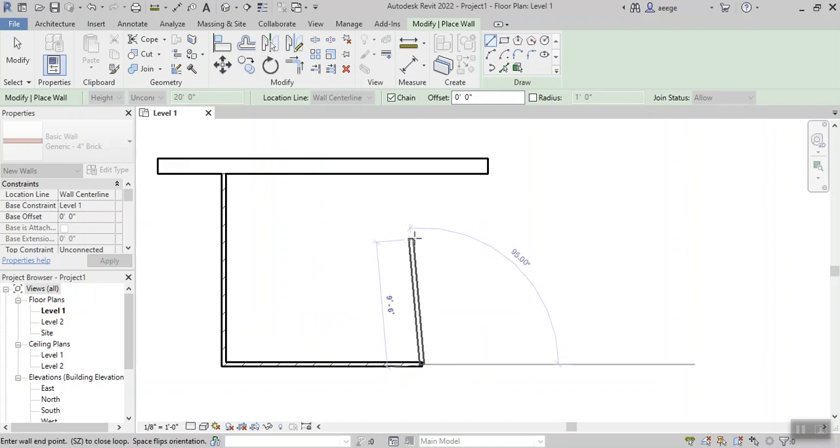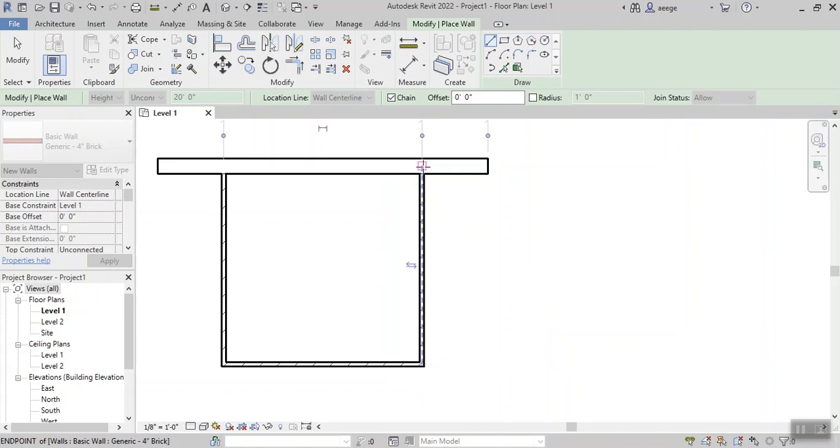Okay, second wall is also created. Now I'm moving my cursor up all the way to the center line of the exterior wall, as perfect as it can be. The computer shows me intersection with the center line with an X. That means anytime I want, I can click on the left mouse button to end the wall command. That's exactly what I'm doing. So the computer right now generated a perfect 3 walls.